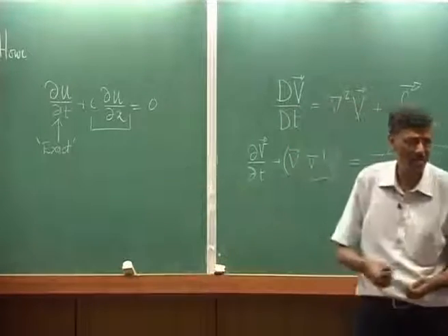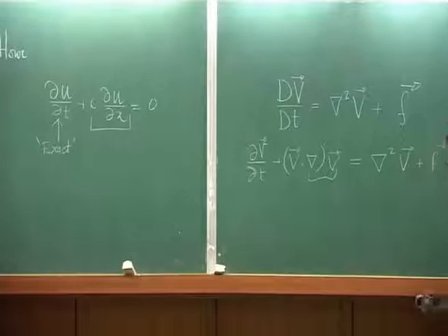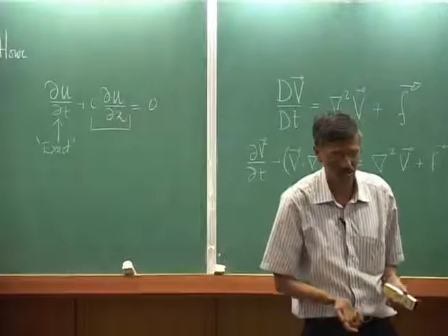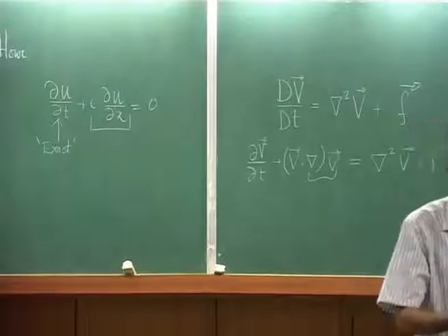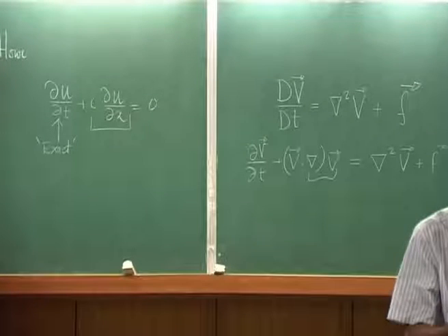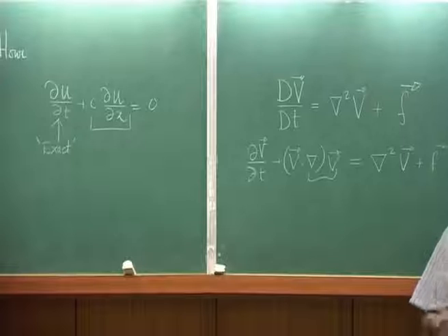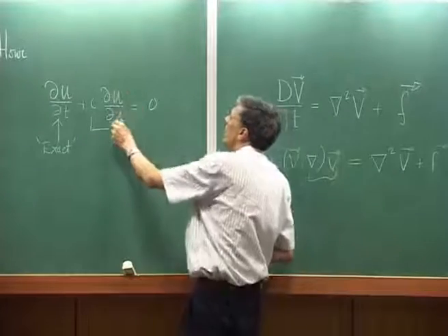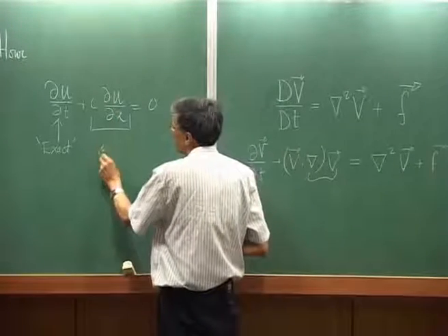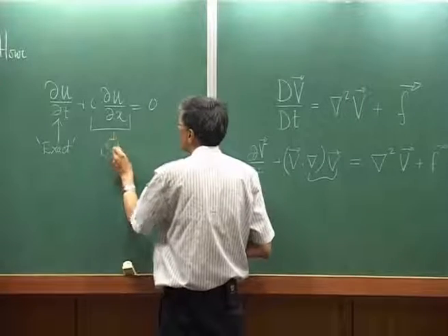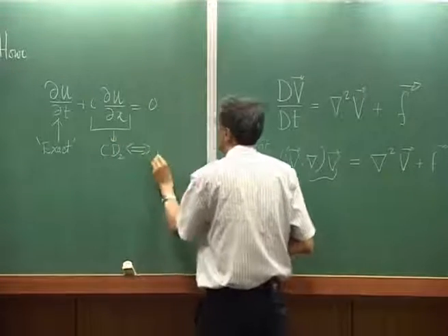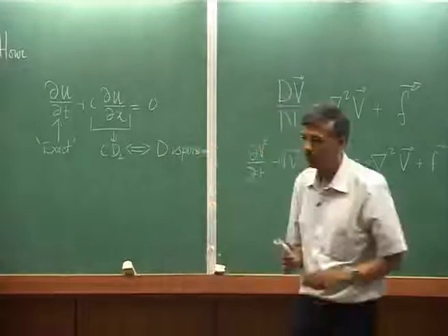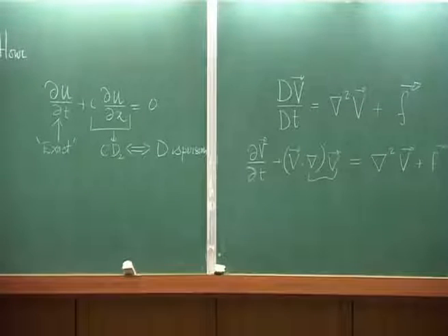And in that context, we had some discussion in a lecture a couple of days ago, where we talked about how if I do first order upwinding, a forward difference or backward difference, I actually add dissipation, and that solution would attenuate, and that is something we do not like. And then we also said that if we do some kind of second order central differencing scheme for this, we notice that this gives rise to dispersion. We discussed it, right. We made that observation.